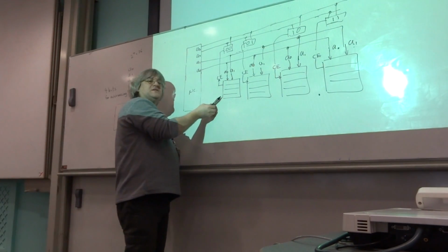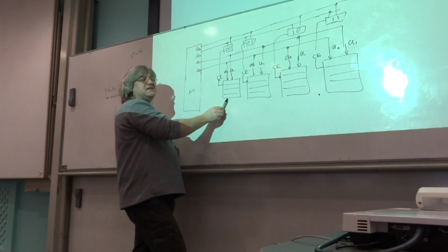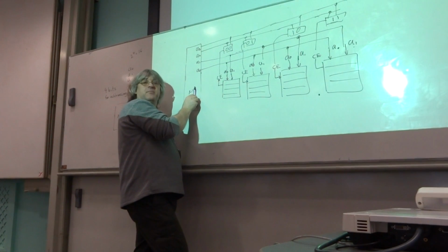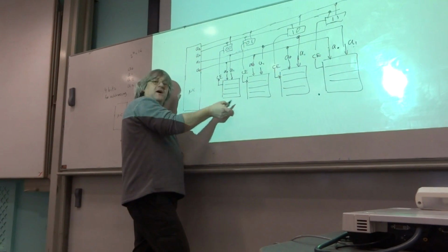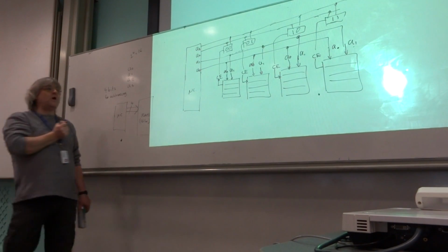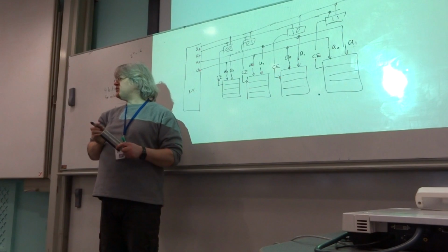That way, I'm using devices which are smaller than the size of my memory map for this processor, but I've arranged them in such a way that they each occupy part of the memory map. And I've arranged it in such a way that at any point in time, no two can ever be switched on.